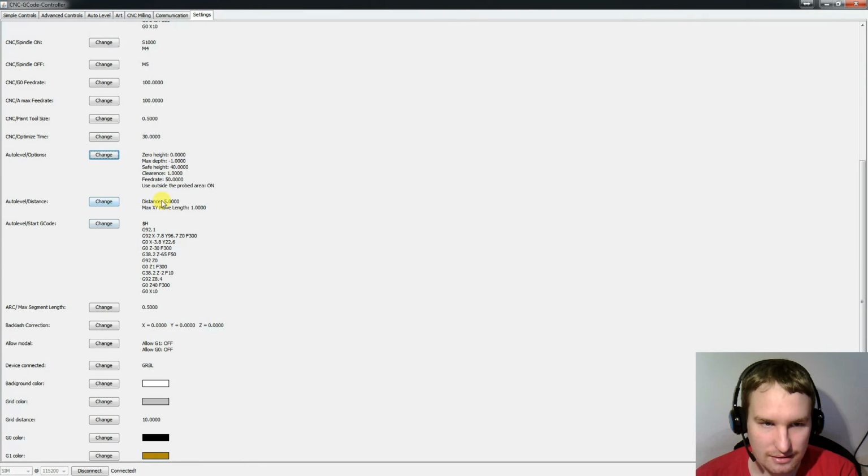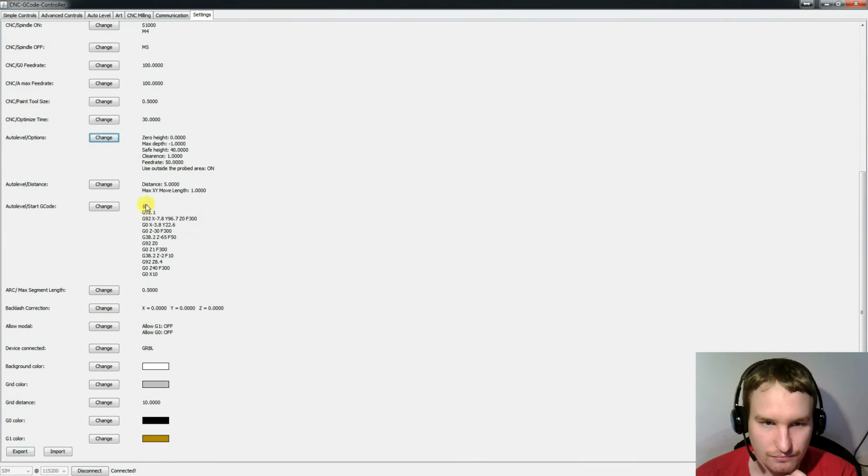And this is also important when you do the auto leveling and, for example, one milling move is really long. Then these settings will cause the moves to be split into separate moves, and each move gets height corrected. So when you have a high resolution and you make a lot of probing, then you should also decrease this distance so that long moves also get really high precision.